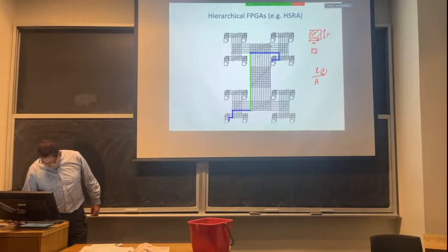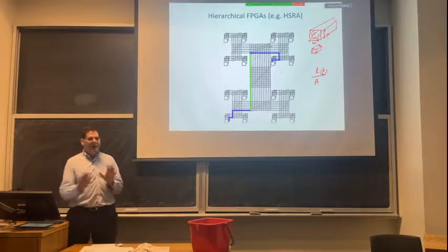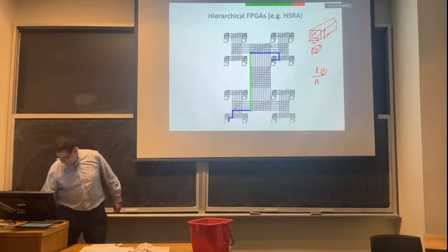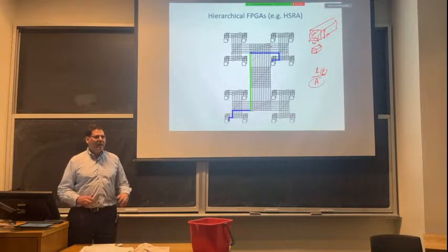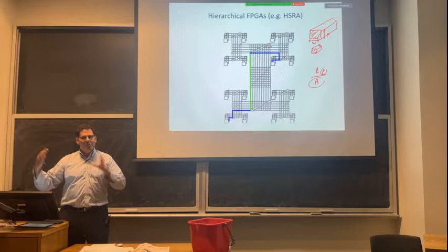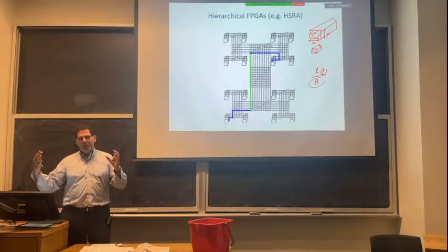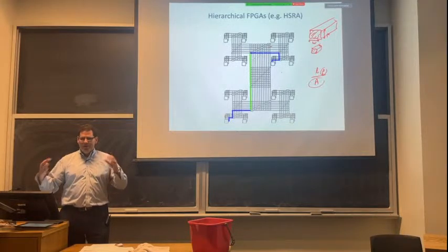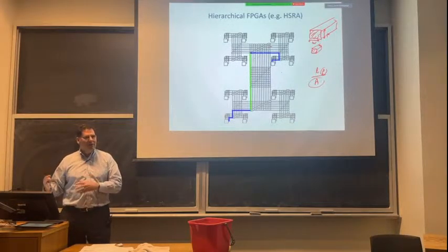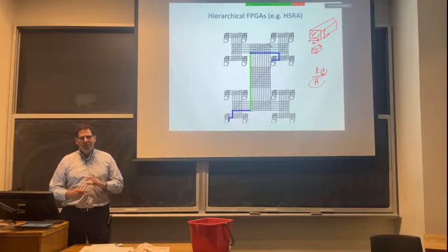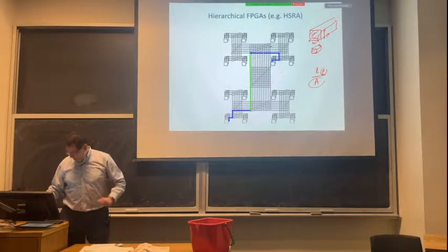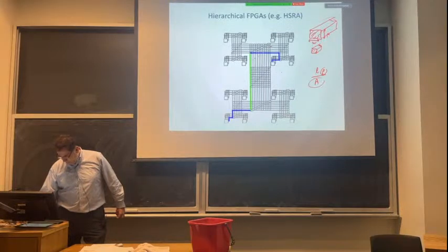Length, as we scale the process, we actually have some good news. The length gets shorter, right? All our circuitry compacts, the wires get shorter, that's good. But this area is bad news, okay? Our resistance goes up quickly because the cross-sectional area goes down by the square. If I scale the process down by 0.7, every dimension gets 70% as big as it used to be. My area is actually half. My length also goes down by 0.7, but it means my total resistance of this wire actually goes up when I scale from that to that. Does that make sense?